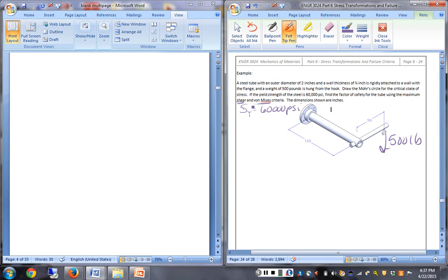But we know what is the shear force. We know it's 500 pounds. How much are the moment arms? They're bigger than an inch. So just looking at it, you can see that those resultant moments are going to be thousands, not hundreds. So just rough order of magnitude, you know that that V term is going to be down in the noise. So we can say we're not going to deal with the shears.